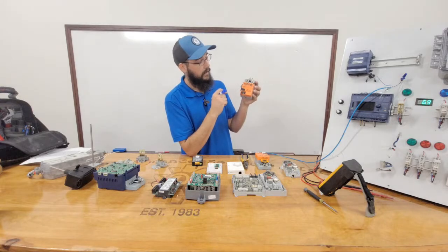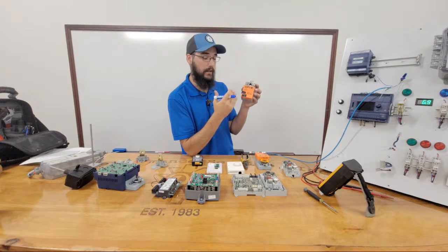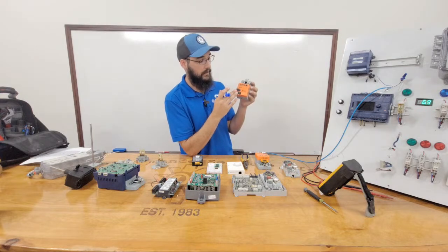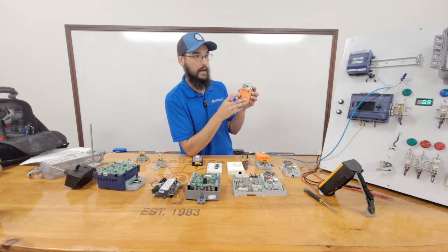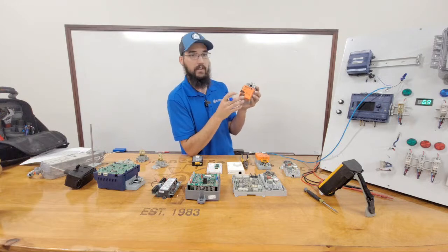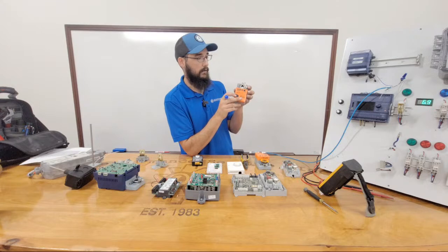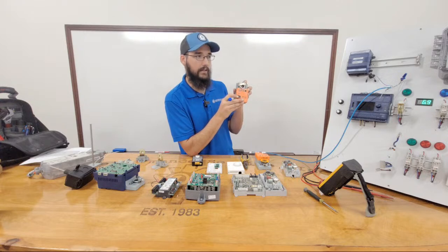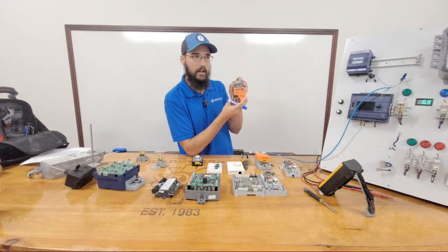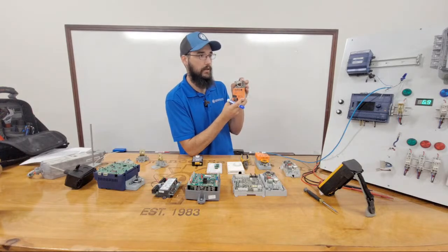Now, if I didn't want 100%, then I could split that 95 in half and say I just give it a 60-second pulse, which I know is not half, but you get the idea. Then that actuator will move, and once it hits 60 seconds and I drop the voltage, it's going to lock into that position, and it's not going to go any further.